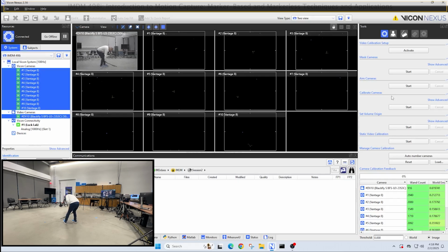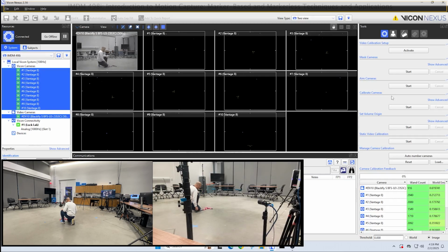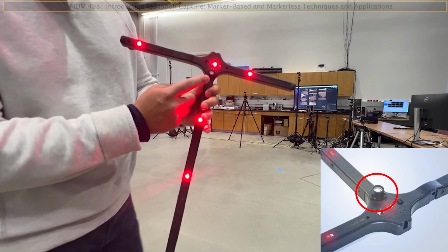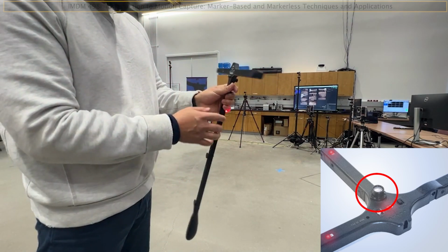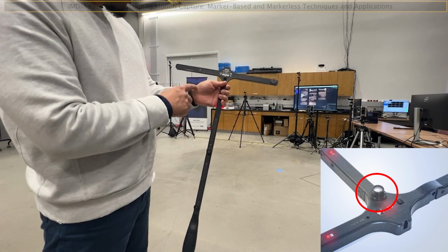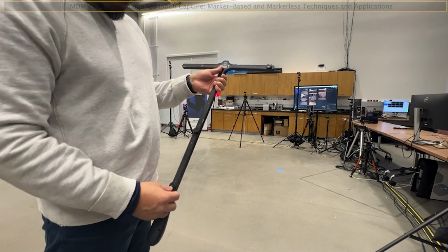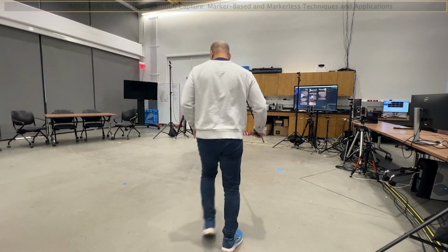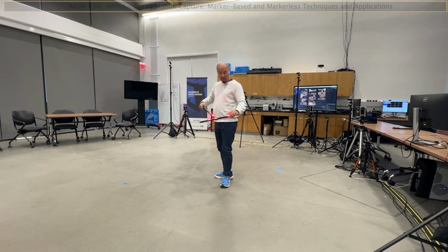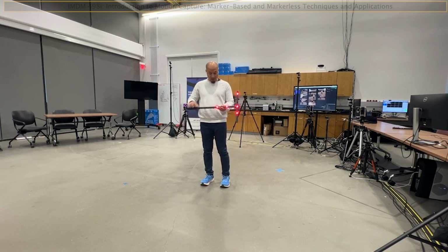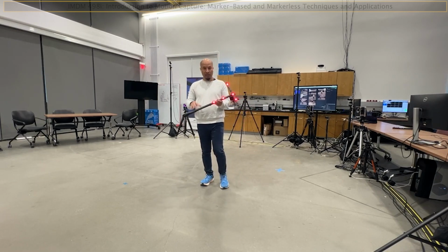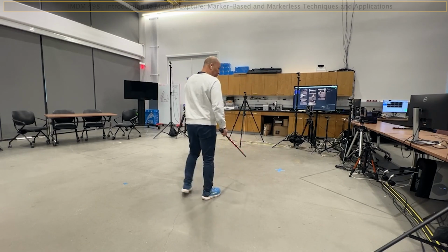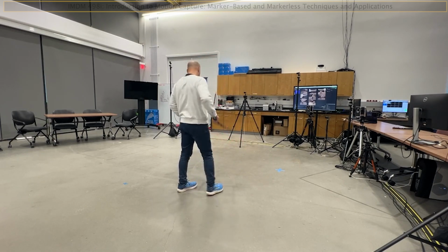The nice thing about Vicon is that it does both intrinsic and extrinsic calibration. Now, what you cannot see from the camera, but I will come close, is that there's a little bit of a leveler here. You see the leveler? We have a couple of settings here, and we're going to lay this flat on the ground. It detects these IR lights, and it knows the offset from this to the ground, and that's how we set the floor. Similar to how we did it with the calibration board, but in our case, we will be using this.